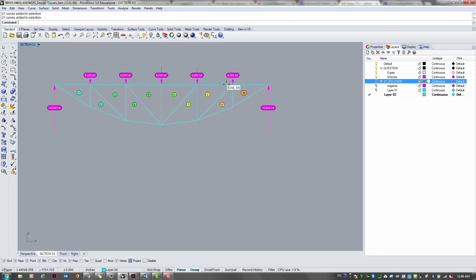The efficiency of that is, if you design it such that all of these have same internal force, you can basically use the same member size, right? Depending on what material and the cross section, you can calculate the stress, but the stress along this top chord is constant, so you're guaranteed to be able to use the same size all the way across. Otherwise, as you remember, the rectangle ones had bigger compression on the top chord in the middle, right? So you might have had to use a thicker member in the middle.